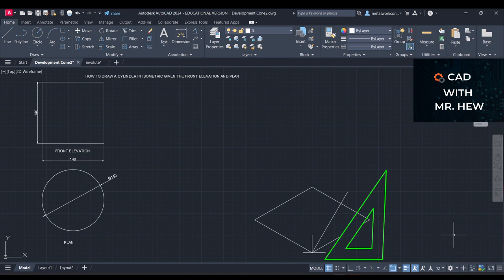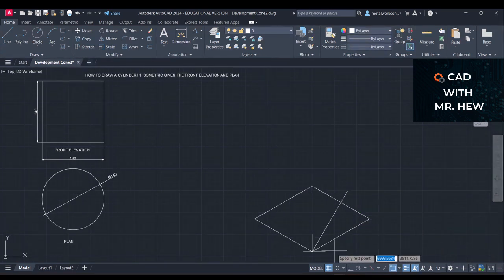This is how you would align the 30-60 set square on the t-square. The t-square will be horizontal below the green 30-60 set square, the triangle looking object. I would slide it to the starting point to give you this 60-degree angle. We're going to draw the 60 degrees from the starting point, 60 degrees to the horizontal, or the t-square if you're using a t-square. So we set out our 60 degrees. There it is. Good job if you're following so far.